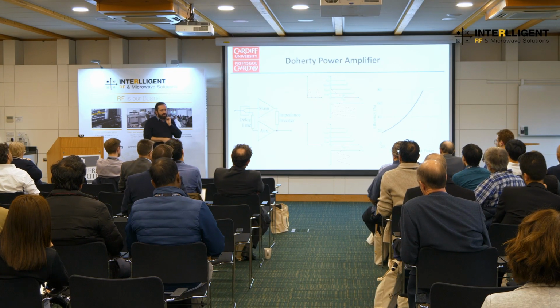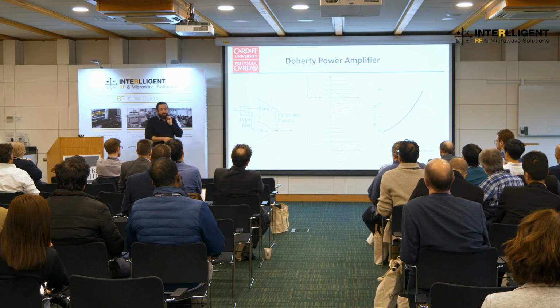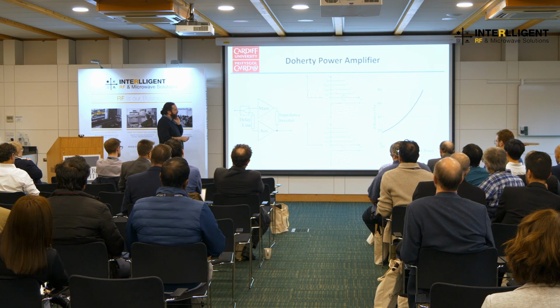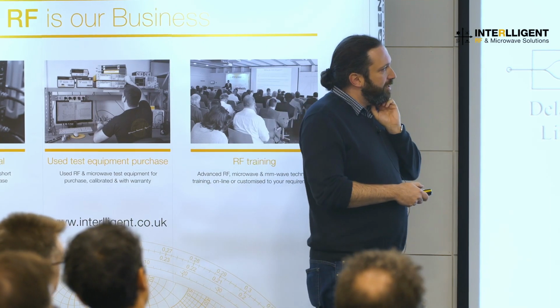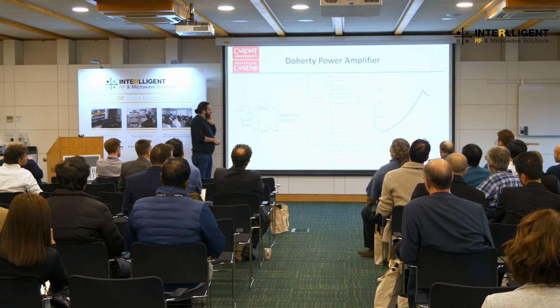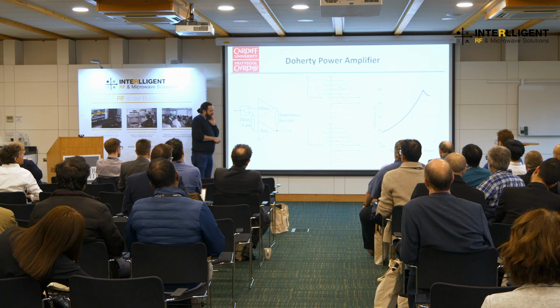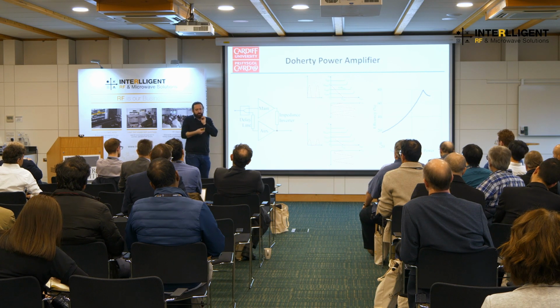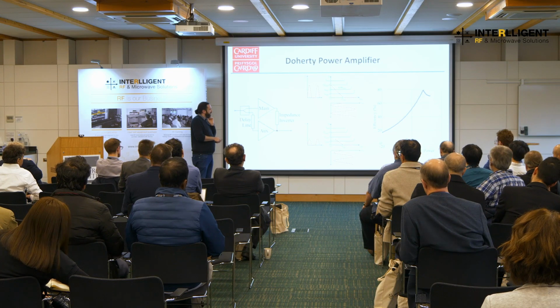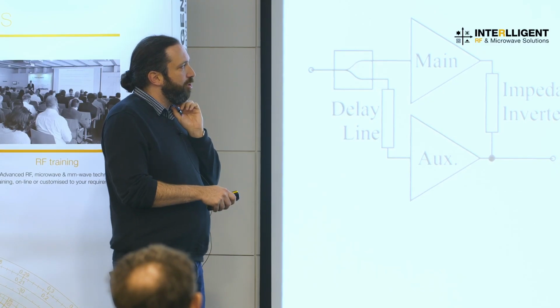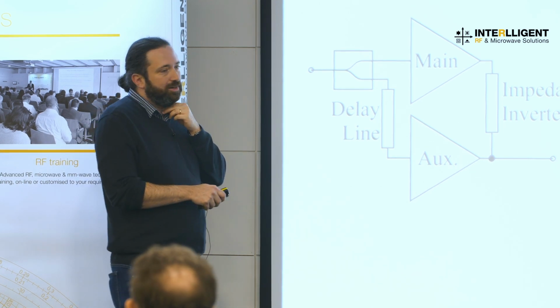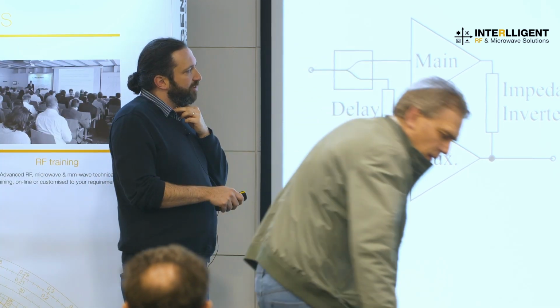Normally, with a normal amplifier, that's where you would stop if you want a linear response, right? So the Doherty allows you to go a bit further. What happens then is that the auxiliary starts to turn on, so it starts to have a current, starts to inject a current into this common node here, and it induces what we call a load modulation on the main. So the slope of this curve changes from what we call 2R up there, changing down to a lower value.